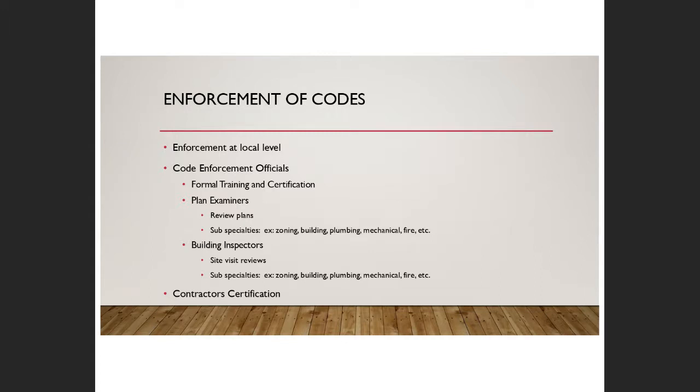The other piece of enforcement is the inspector. There will be building inspections done along with the building permit, again, depending on the nature of the work. Let's say you're building a house. My guess is the inspector is going to want to see your excavation before you pour the footings for the foundation.